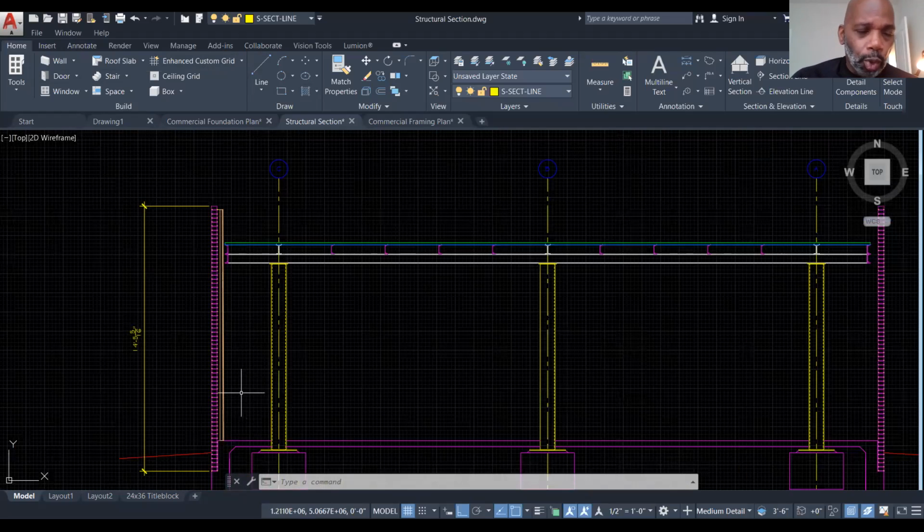So now, what's supporting that gypsum sheathing is metal studs, and what's the spacing of those metal studs? Every 2 feet on center. Is that what it says? Yep. It says 4-inch metal stud, 2 feet on center.